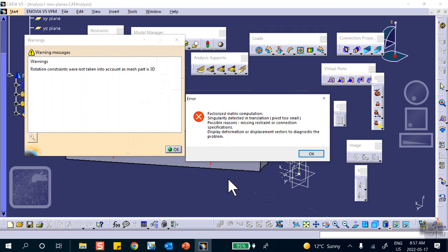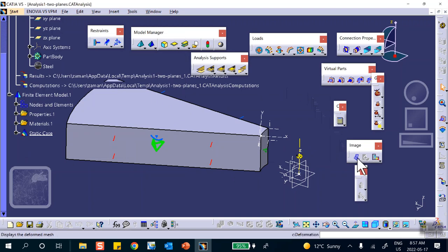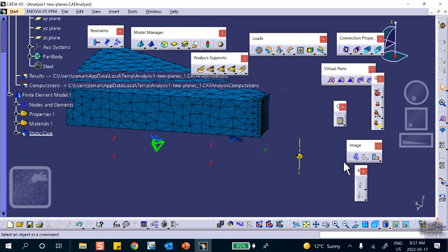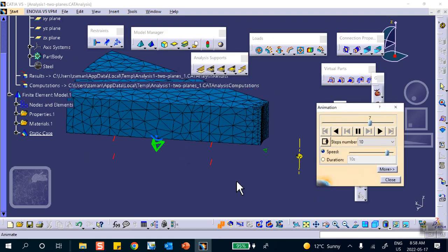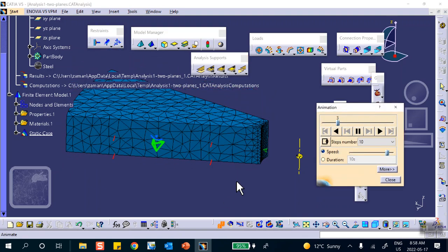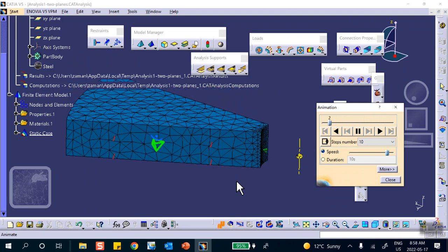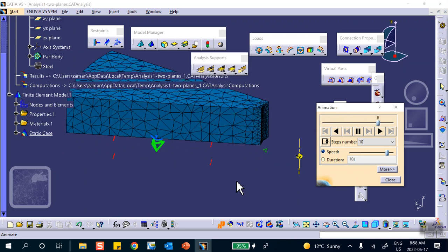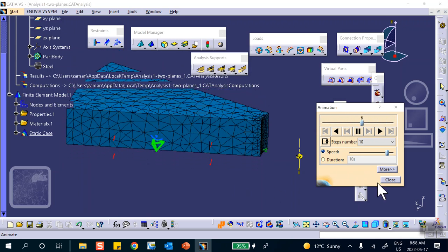It can go up and down, right? As a matter of fact, if you don't see that, well, Katia will give you a hand and say, okay, show me what happened. There we are. Because the ends are on rollers. If I had used a third plane of symmetry with a roller on it, surface slider on it, this would not have happened. But I still have to fix it. I want to do it like that. So take away that rigid body motion.